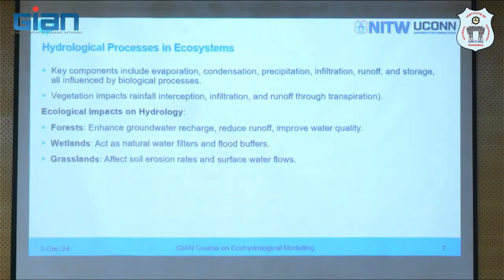Because when you're working as a hydrologist, you're looking mostly at non-biological processes. It rains, and therefore 30% of that is runoff, right? How is that a biological process? Vegetation impacts rainfall interception. In the Amazon rainforest, as much as 40 to 60% of the rainfall can be intercepted, and it never reaches the ground, and then it evaporates. It's not transpiration anymore. It's intercepted and it evaporates.